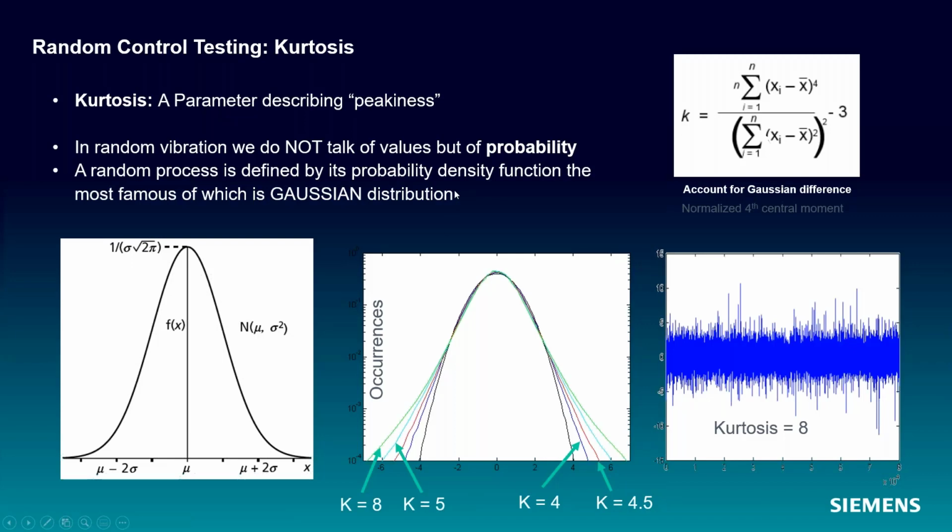What that really means is if you look at the time domain signal and you count the number of peaks and how many standard deviations they are away from your RMS value, and you plot those in a histogram, a Gaussian distribution of peaks, which is our typical random vibration test, is Gaussian random, we get this bell curve distribution where pretty much inside of 5 sigma or 5 standard deviations, we have 99% of our peaks, and you have less occurrence of higher peaks the further away in standard deviation you go.